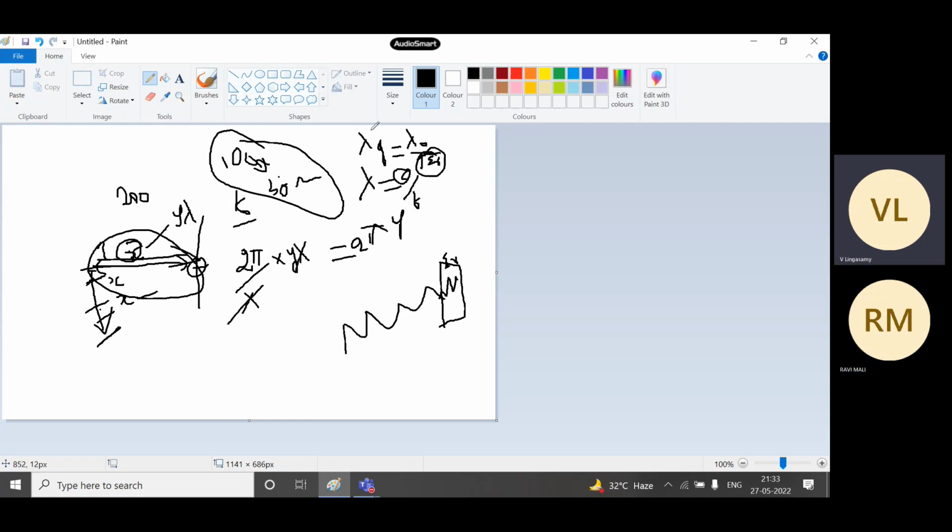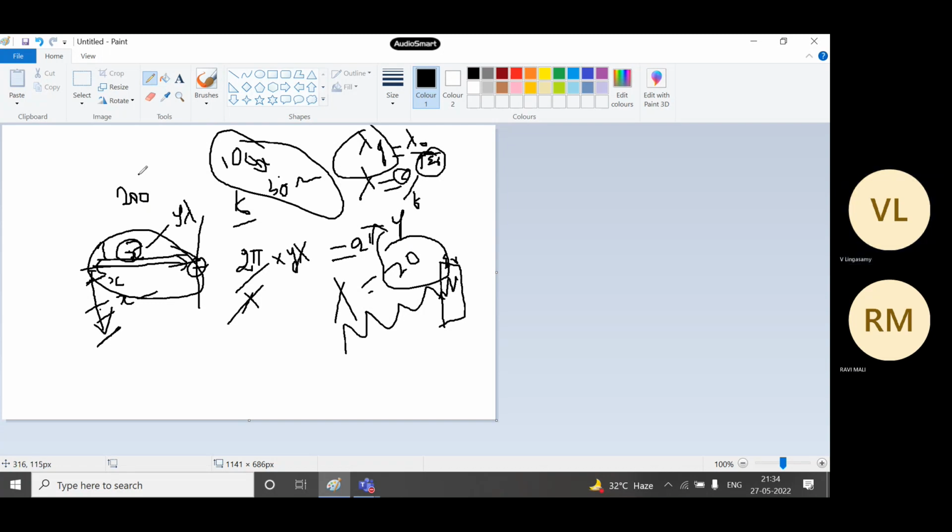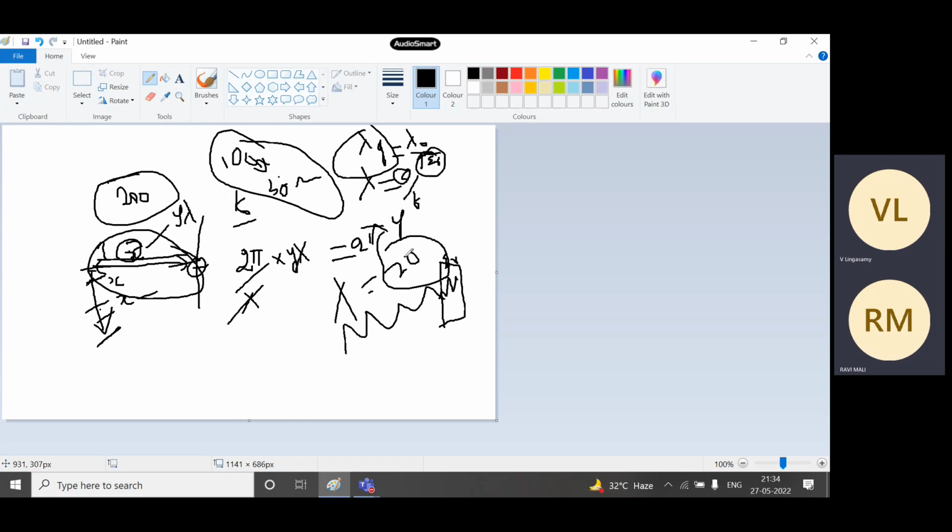Okay. Now, this is the guided wavelength. So now, let's say the guided wavelength of this case is, for example, 20 mm. Okay. So now, 200 mm was the length, right? So now lambda g is 20 mm. So how many lambda do I have? 10 lambda, right? If you are representing the total length in terms of lambda, it is 10 lambda.